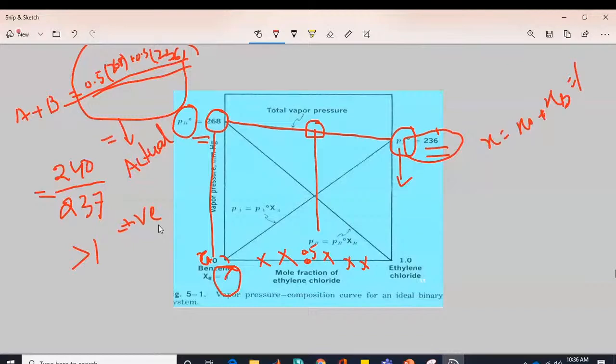Uses. Now this is the thing that we need to go through. Flash distillation is used for separating components which boil at widely different temperatures. Right, I mentioned like C5 and C10. Now there's a big difference. If they are very close, then it's very difficult for you to get bigger purities. At this one, you cannot get the bigger purity. But for this one, definitely you're going to get bigger purities because the boiling point difference is too high.